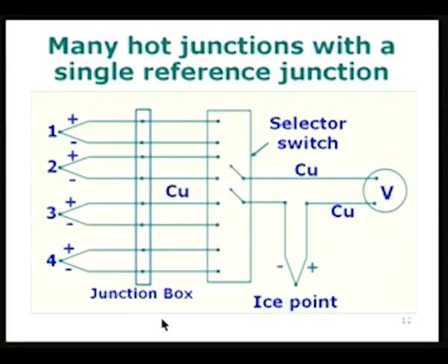In fact, if you look at the sketch, all the three different laws of thermoelectric circuits which we talked about earlier are all applicable here. In fact we have several junctions that have been formed. We are seeing to it that all the junctions are at the same temperature by using the junction box concept. We are using a good selector switch, which is also usually a very bulky item, whose temperature will remain more or less uniform throughout. So, these are all some of the things involved in this particular measurement.